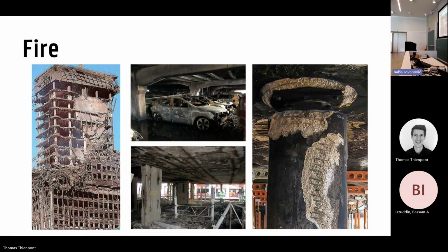And it's also important to mention that as a structural engineer, fire can also be a very severe event to a structure. It can cause damage, like the damage that you see here, but it can also deform members because of the heating. They lose their strength and it might lead to partial or complete collapse of a structure.